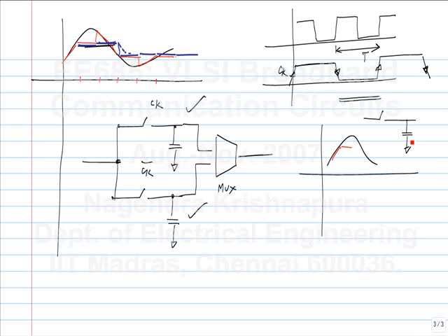Similarly, by having two track and holds operating at half the rate and multiplexing the output, you can also get a sample and hold. So there is no tracking part that is visible at the output of the multiplexer. You will have to use it such that when this clock is low, it lets this through, and when this clock bar is low, it lets this part through.